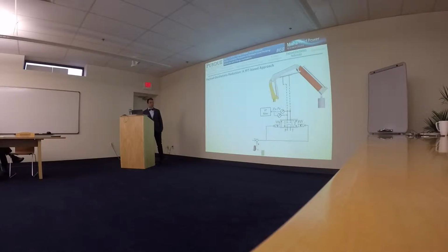And so here is the controller strategy we implemented. Again, we have this low-pass filter logic, where we use this low-pass filter and this logic here just to select which pressure we want to use. Once the pressure is selected, we perform an FFT estimation and a peak detection. The FFT is not something tricky; we had to use some windows and manipulate the pressure signal, and this again is explained in much more detail in the thesis. The peak detection block just detects the peak associated with the payload oscillation.